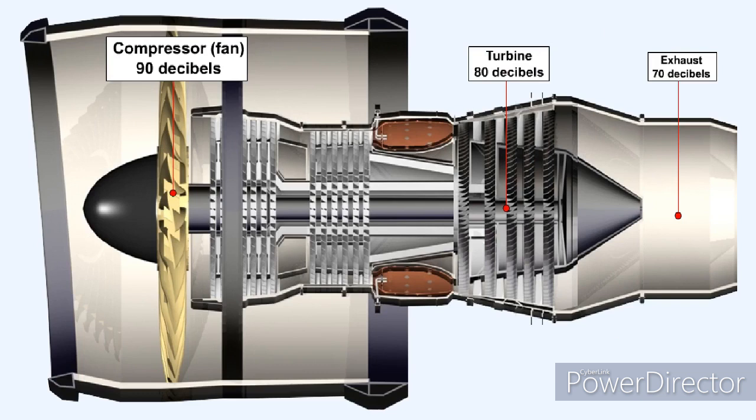In the case of a high-ratio bypass engine, say an engine with a 5:1 bypass ratio, the noise from the jet exhaust has been reduced to such a degree that the noise from the low-pressure compressor, the fan, and the turbine are now predominant. Having reduced the noise levels emanating from the main source, the exhaust, engine manufacturers then concentrated on lowering the levels of noise from the rest of the engine, specifically the fan and the turbine.